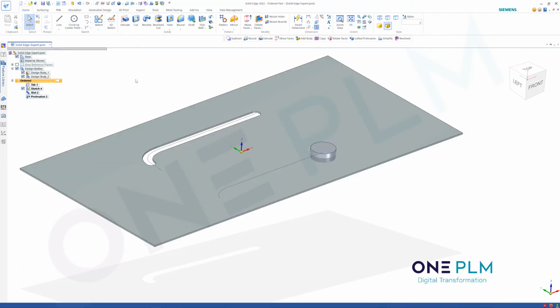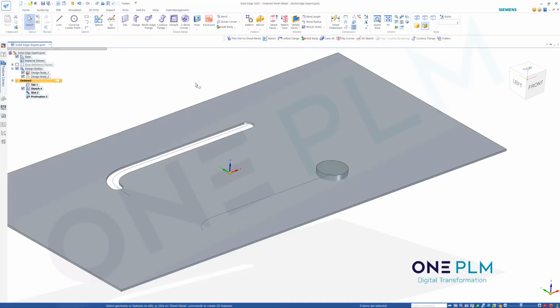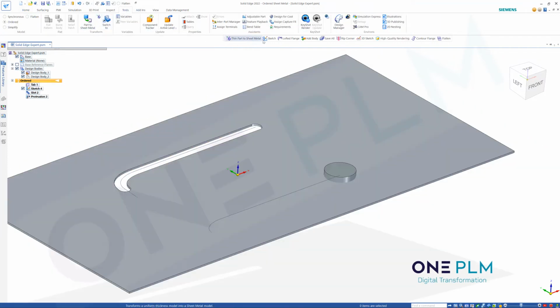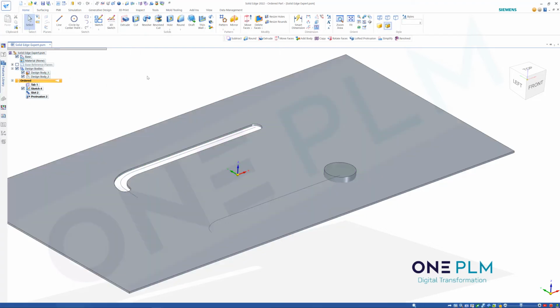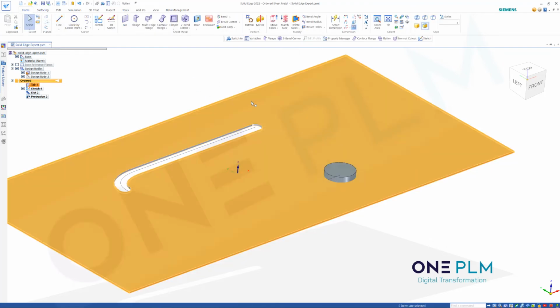So if we double click back on the design body one in the sheet metal, that will take us back into the sheet metal environment. You will find if you do this quite a bit, this little switch to will end up here, but you can see I've actually added mine up here. So if we need to do a switch to, we can easily just switch between those environments. But remember, the design body option also will allow us to switch into the appropriate environment that it was created in.